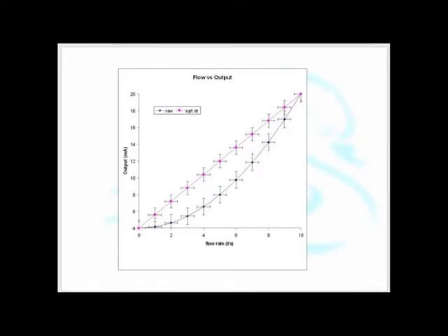When we're using pressure to calculate velocity and velocity to calculate flow, with differential pressure type flow meters, there is a square root relationship between the flow and the pressure. So the relationship is flow Q equals square root of pressure times a constant.